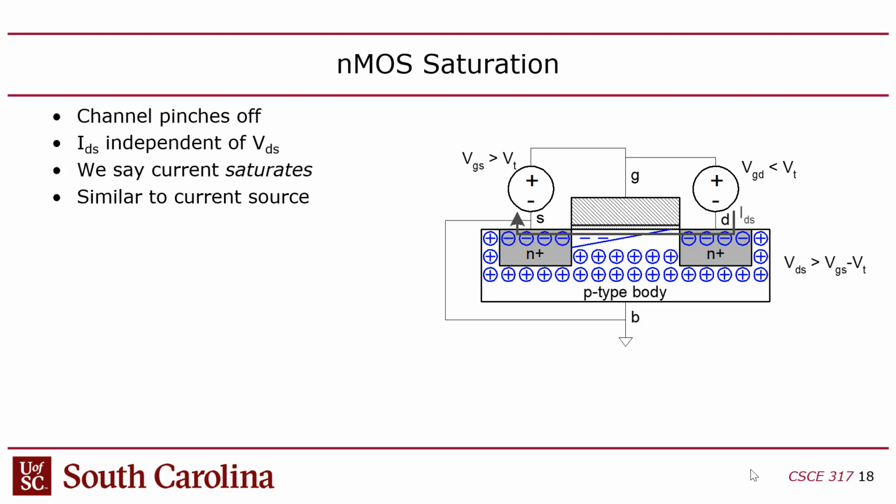remember, the problem, again, is that you have to look at the average voltage across the channel. If there's a big difference between the two sides of the channel in terms of the voltage, then this side of the channel, between the gate and near the drain over here, will become pinched off because the drain is really high. The drain voltage is a high voltage that's going to be close to the voltage of the gate, right? So the voltage difference between the gate and the drain, or at least in this half of the channel, is going to be small.